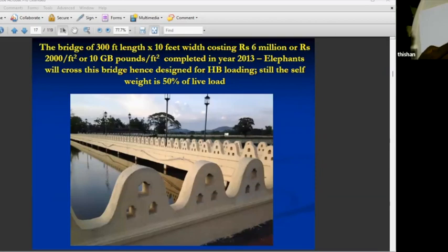And this was constructed during a time when this reservoir was emptied for desilting. Because of that, we had a small advantage when we were constructing the foundations. Foundations are all combined footing with columns coming up, and I think 3 columns came because the total width was about 12 feet.